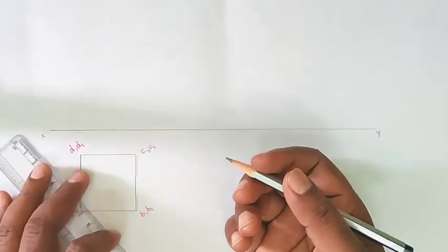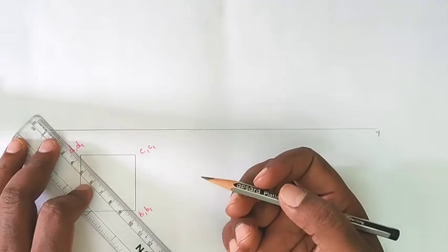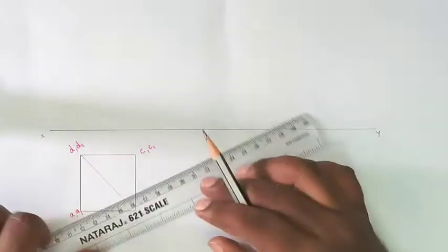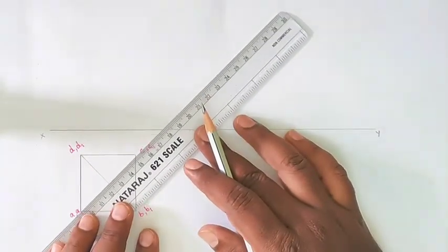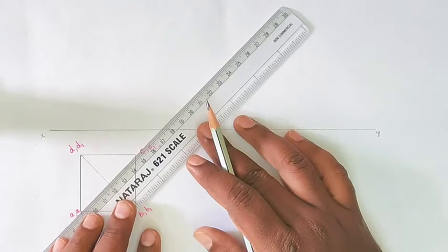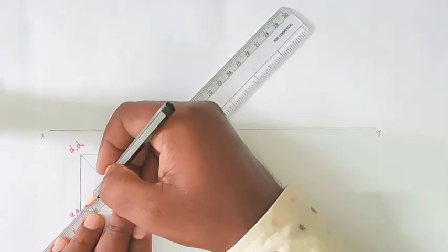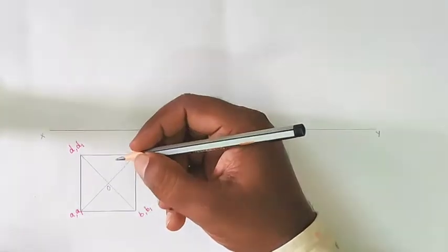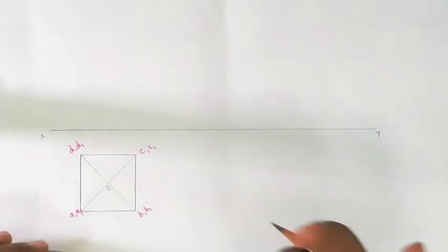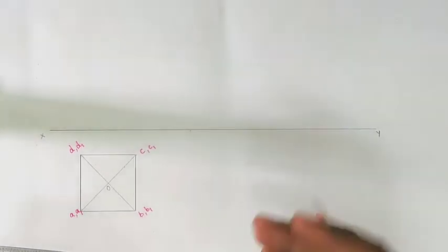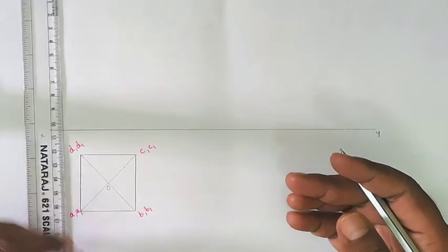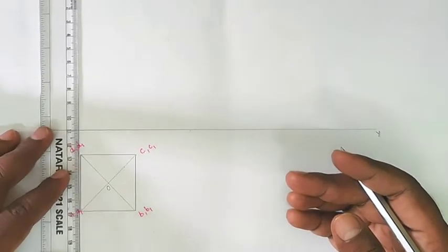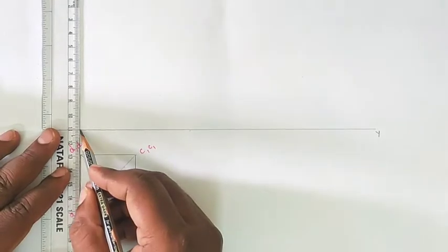After drawing the top view, locate the center point by joining the opposite diagonals. In a prism, the inner diagonals should be drawn very thin. Only in the case of a pyramid, the inner edges from the center to the corners are also thick lines. In the case of prisms and cylinders, we draw the inner edges very thin using our 2H pencil.